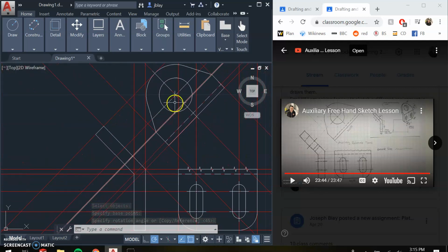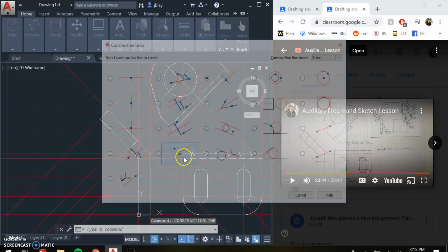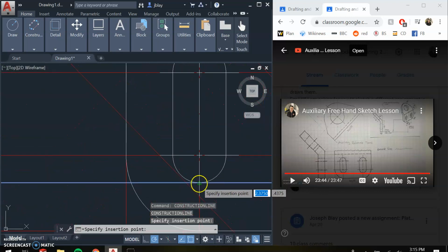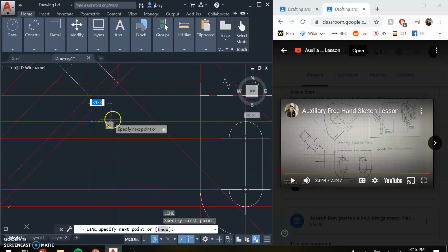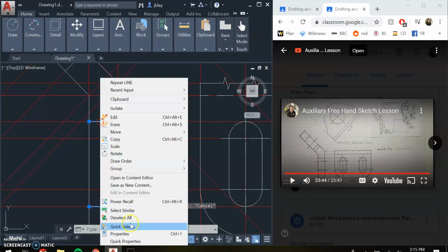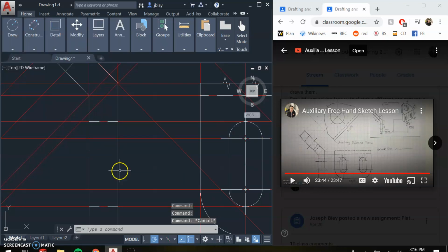Great. Now let's add our hidden lines to our right side view, not our right side view, our front view, starting with the ones for the slot here. So we'll add horizontal ones here, and we'll draw lines. Select them, go to properties, and make them hidden. Ooh, I made them continuous, which they already were, hidden. And then I need to make the line type a construction line.